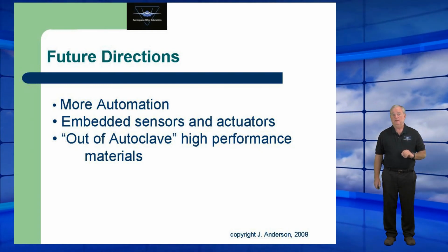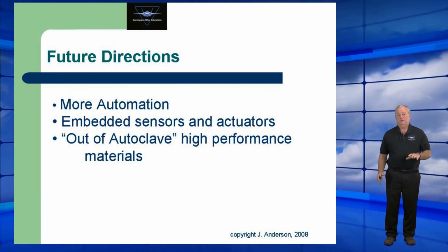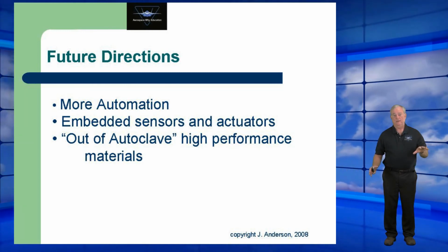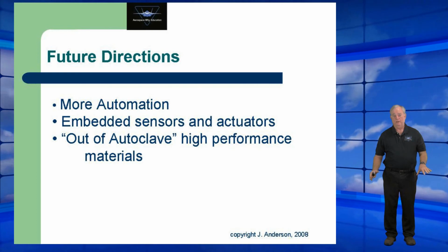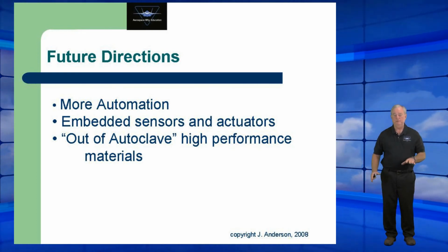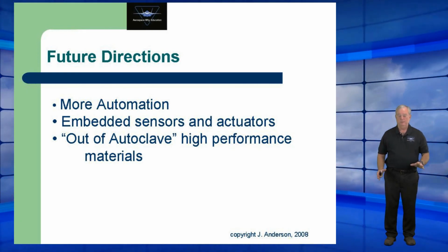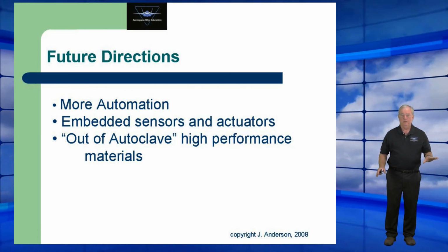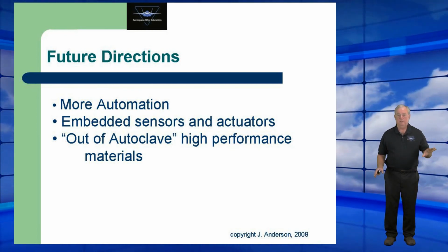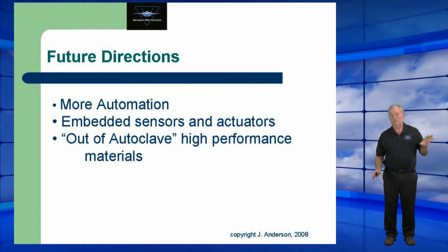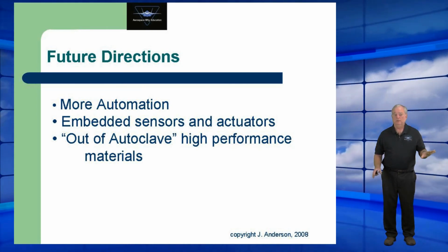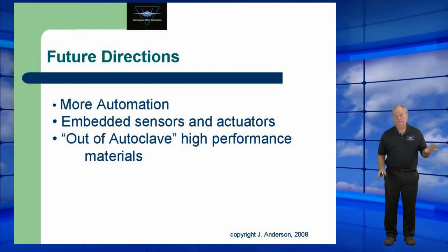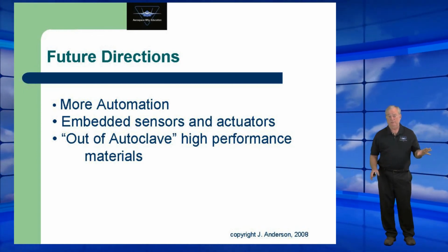So as we stress the aircraft, when we start to reach the stress limits, how can we record that automatically? There are G meters; current production uses accelerometers mounted overall in the aircraft. But how can you tell how often you're flexing the wing structure in a way that will cause cumulative damage or cracking, fatigue damage in the resin?